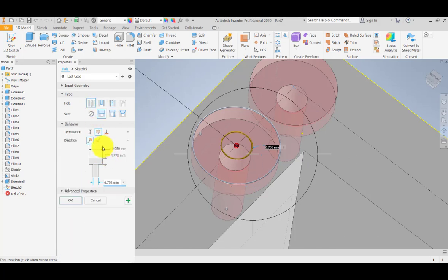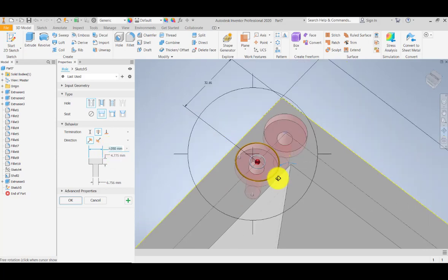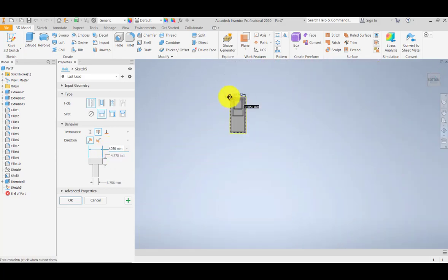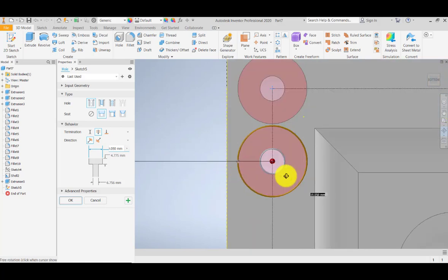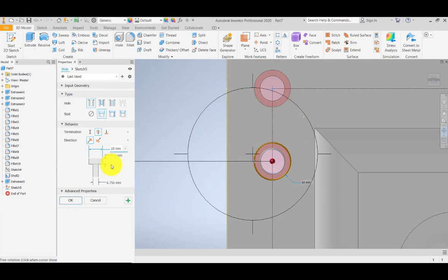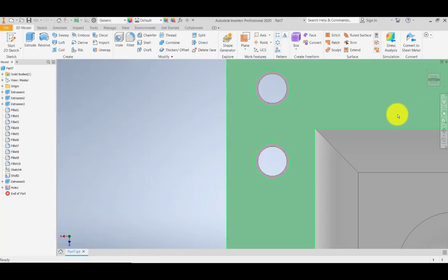So you'll see the diameter, which is 19 mm. If you check that one, 19 mm is too big, so we'll reduce the diameter. Here you can see the thickness, so we can assign, let's say, 2 mm. And this one is the distance, the diameter of this. Let's put about 10. Then we have 6. Usually we can write 8 mm here. Then click OK. So we have now your hole.